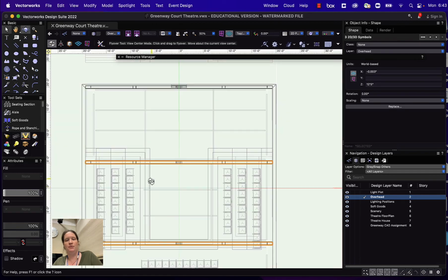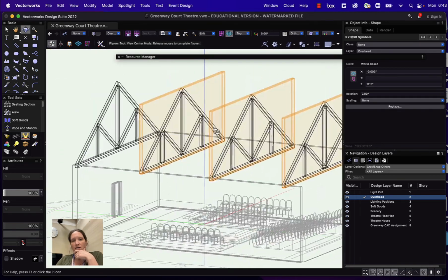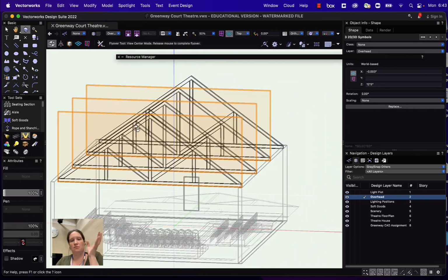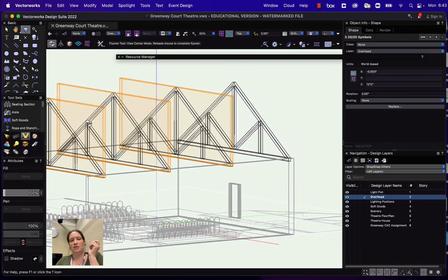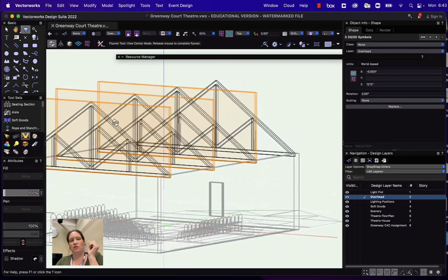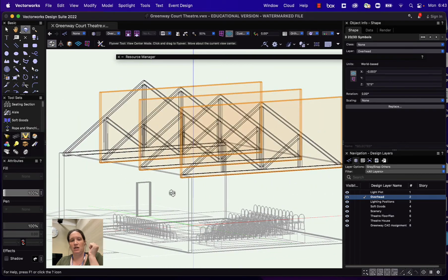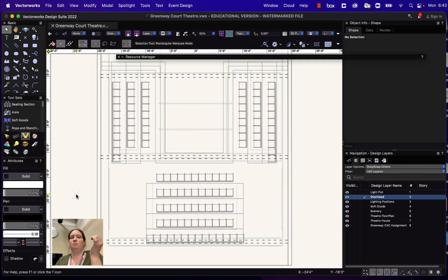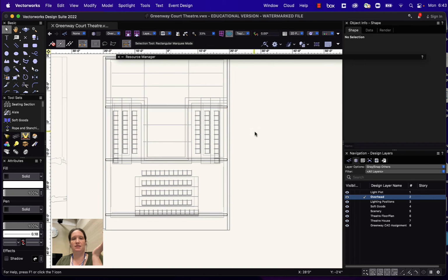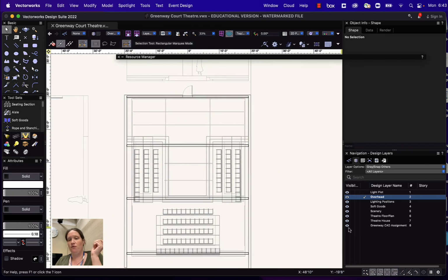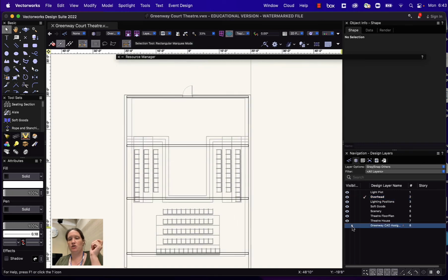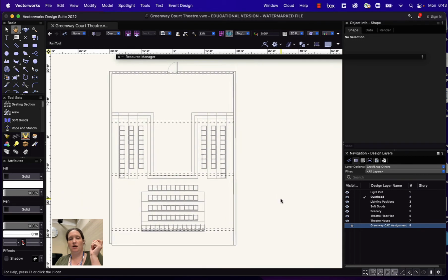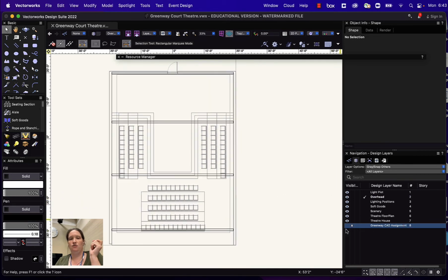Okay, great. So now we have overhead, the gables, the beams, and we have the rest of the space much more clearly drafted. This will then allow you to create your plan view, which would look something like this, and your section. For those viewports, you want to just turn off the CAD drawing, which is no longer the reference.